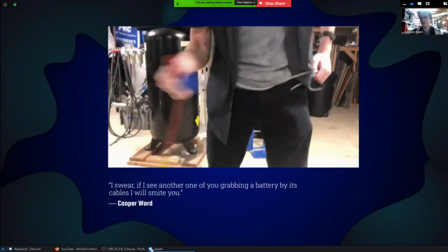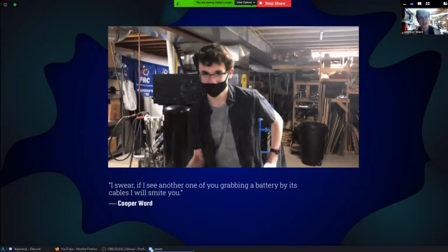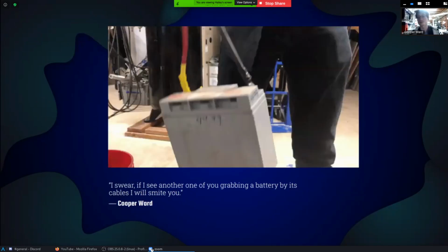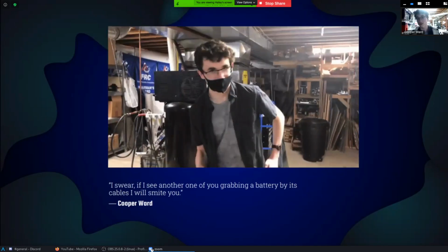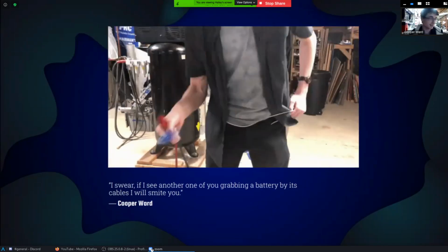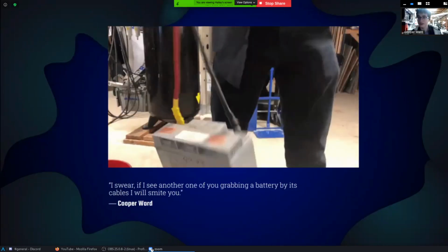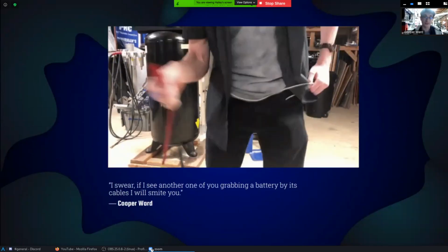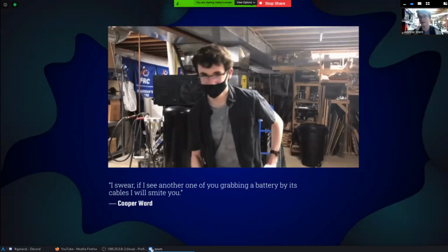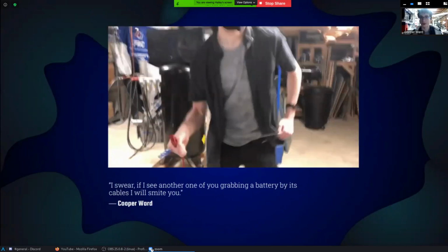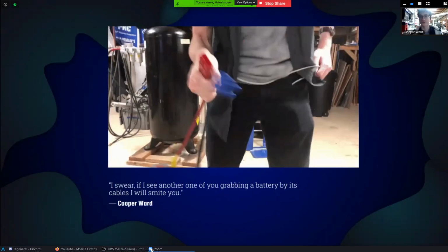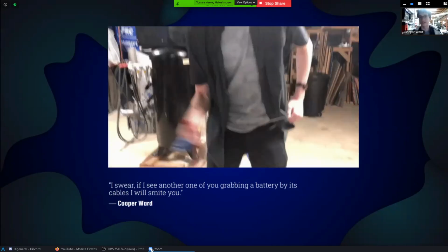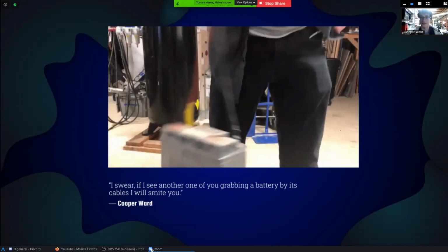And so we have some inspirational quotes that hopefully some of you can relate to. So this is one of my quotes. I swear if I see another one of you grabbing a battery by its cables, I will smite you. And this is because every time I see this, it makes me cringe on the inside. That's because as you wiggle those by the cables, because your hands hurt or whatever, they will break. And then it takes a while to remake them as well as you did before. Constantly having to remake those batteries can also wear down connections over time, causing more resistance, and your robot performance goes down. And also batteries tend to be pretty expensive, especially every season whenever you run them dry after every single match.